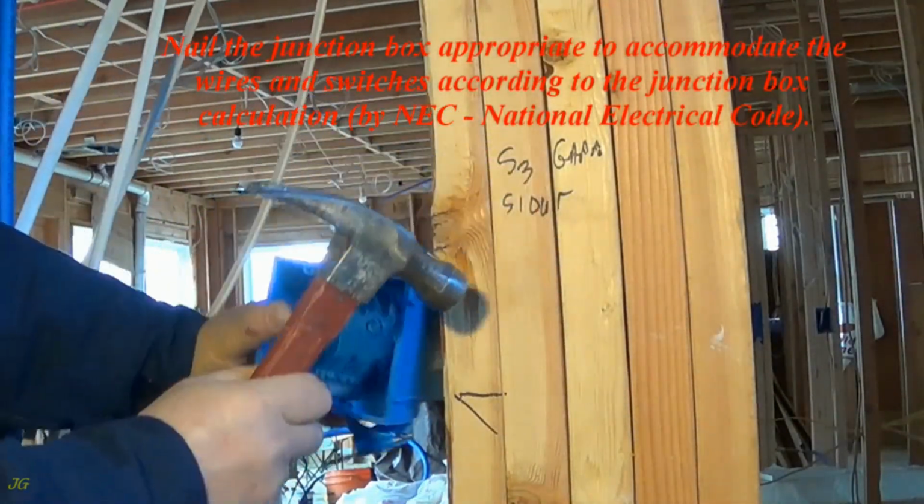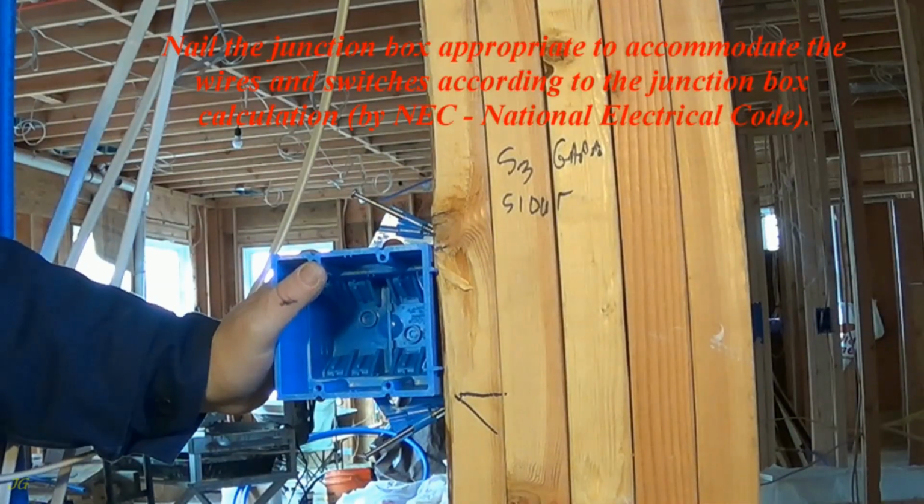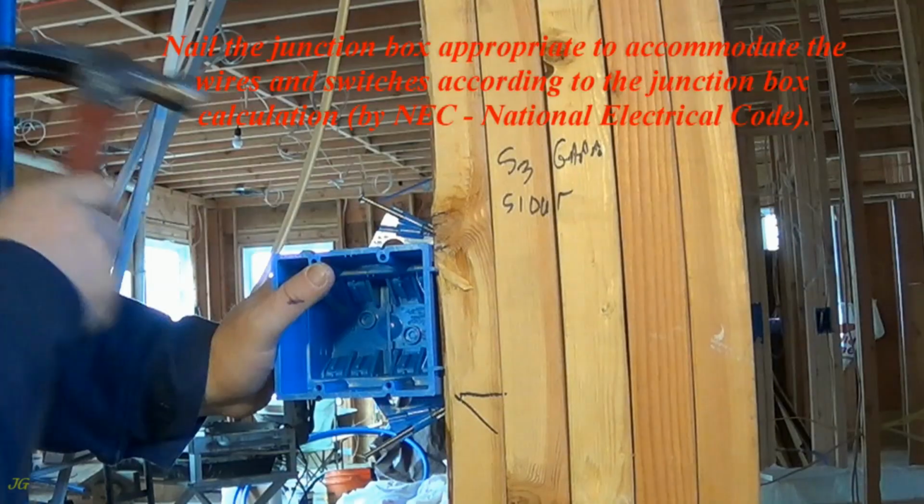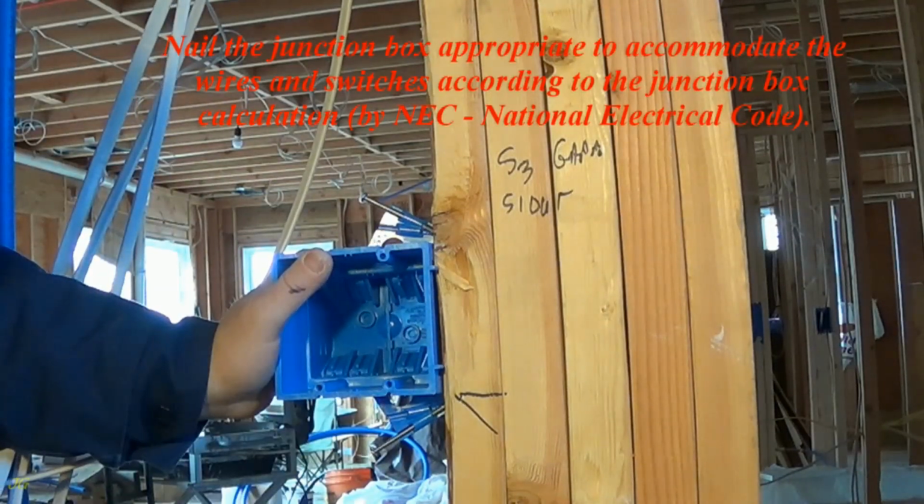Nail the junction box appropriate to accommodate the wires and switches according to the junction box calculation, by NEC, National Electrical Code.